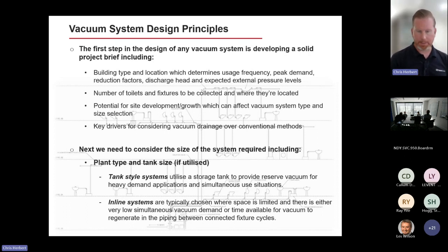So it might sound like a silly one. Aren't all buildings relatively close to atmospheric sea level pressure? Well, no. The guys in France installed a skiers refuge in Mont Blanc, at some crazy elevation up in the French Alps. They actually had a problem with using centrifugal pumps, because we have sea level atmospheric pressure here and absolute zero here.